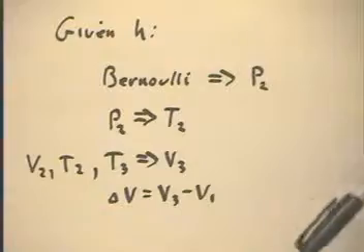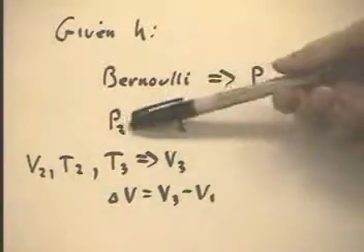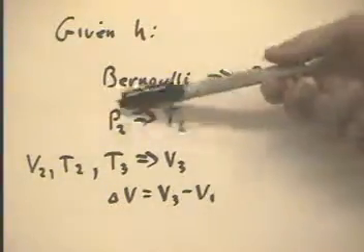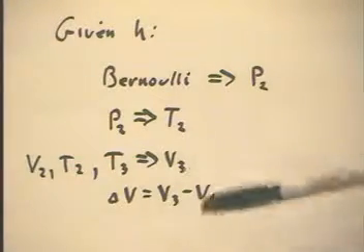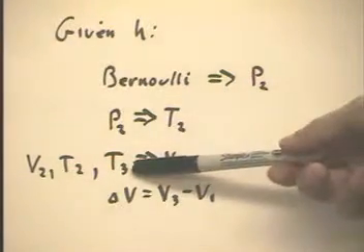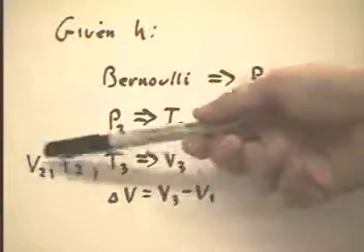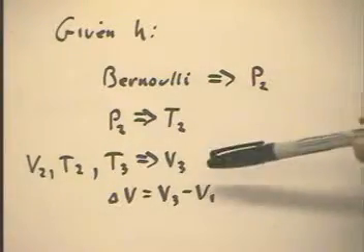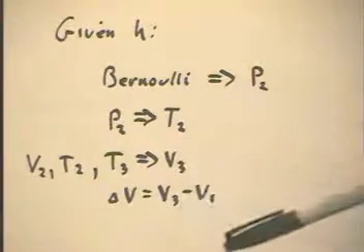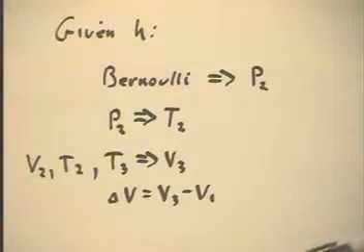We know the temperature T1, the original temperature, so we can easily find temperature T2 if we know pressure P2. Then, for State 3, knowing the temperature in State 3 and the volume and temperature in State 2, and the fact that the pressure remains constant up to State 3, we can easily determine volume V3 by simple proportionality again.